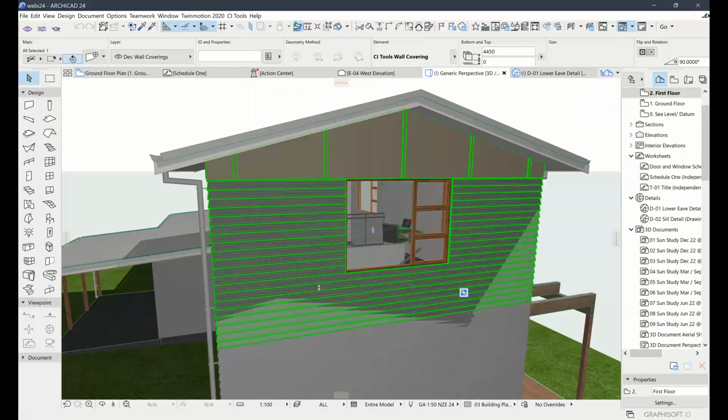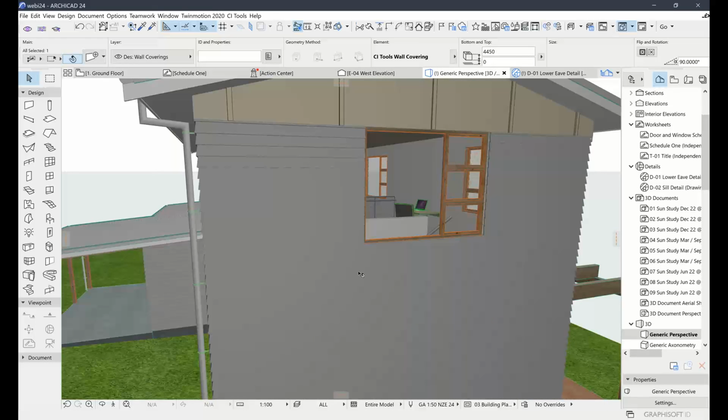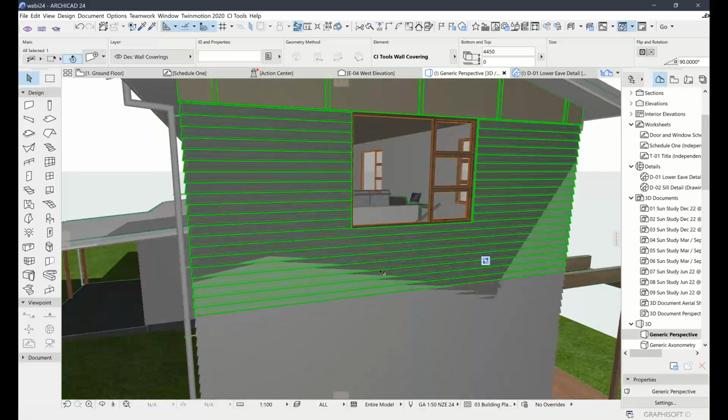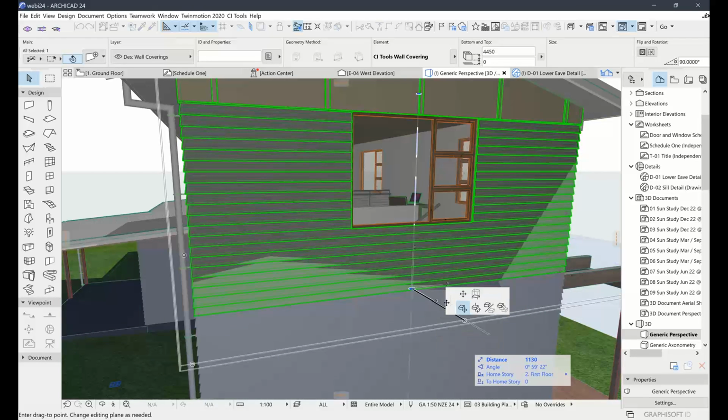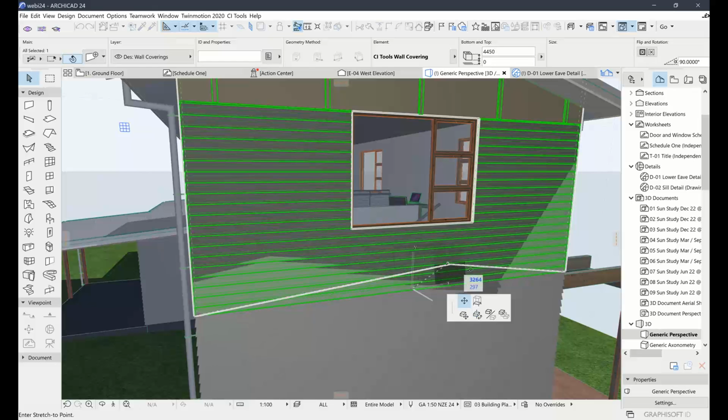And it's going to look like it hasn't done anything, which is normal. But you'll notice that when you have your covering selected, we now have 3 purple hotspots at the bottom of our covering here that weren't there before. What we can do is just click on those hotspots. Once the pet palette comes up, we choose the little free-floating arrow here. That'll let us move the node.